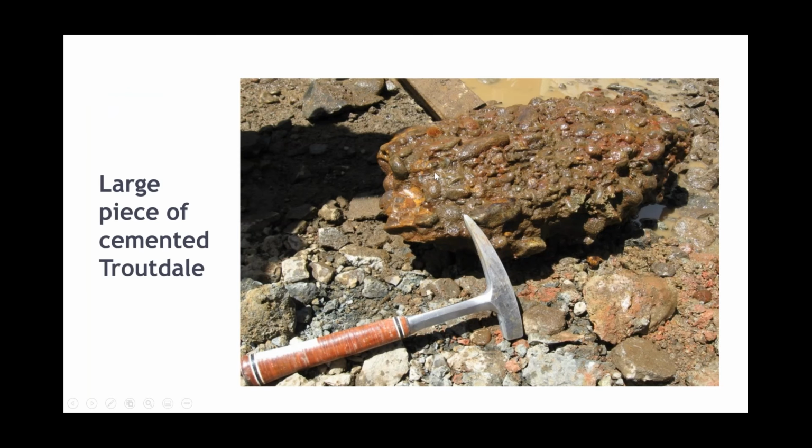A few other photos coming up here about what the Troutdale looks like. When it comes down to additional testing, we had our engineer who was intimately familiar with the design, knew what we needed out of each shaft, and was familiar with the materials. We've got that engineer down in the spoils barge looking at each load that comes out of the grab. And so when you find a nice piece of cemented Troutdale like this, it's very easy to recognize that you're no longer in the CFD.